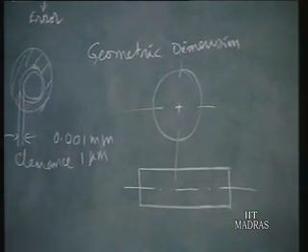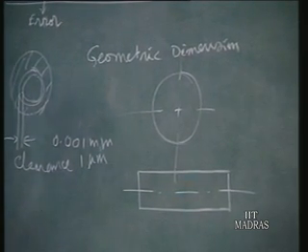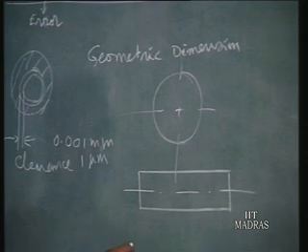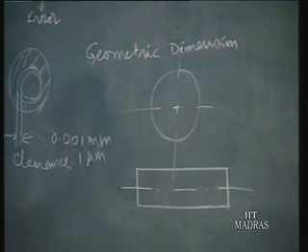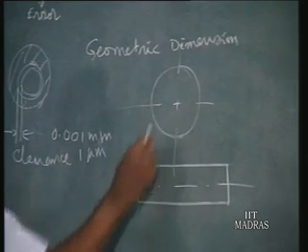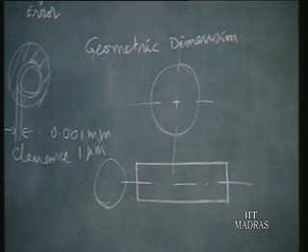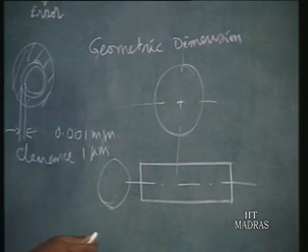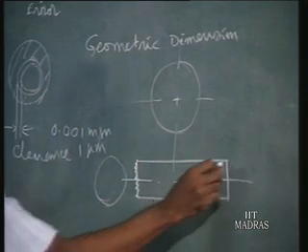So when you want to measure the length of the rod, because this is an abstract geometric shape, we should ensure whether the two surfaces are parallel to each other, or whether the end surfaces, the circular surfaces, are plane, or have ups and downs in their plane configuration. The surface may have irregularities in terms of microns.